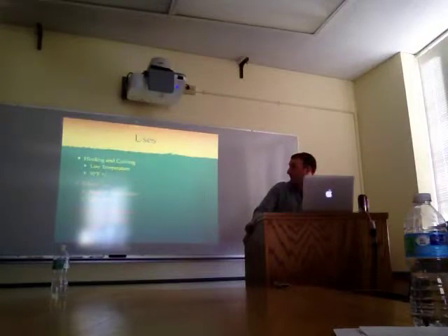Geothermal heat usage is generally categorized by the temperature of the heat source. If it is 50 degrees or lower, it's considered low temperature geothermal, which is typically used for heating and cooling. As you go up and generate larger amounts of heat, you're able to have more uses. So direct uses or medium temperature usage typically fall within a range of 140 to 300 degrees Fahrenheit. And then most importantly is electricity generation. That requires a very high degree of heat, so the geothermal resource needs to be over 300 degrees Fahrenheit.